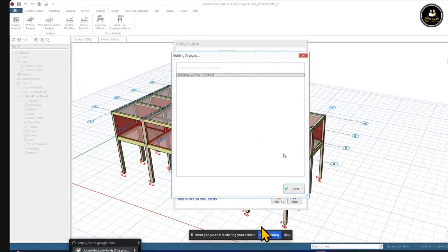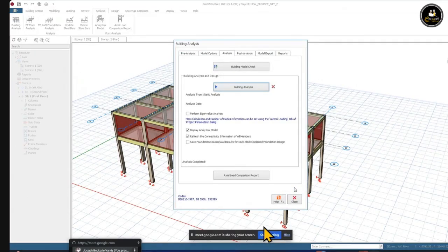Yes, hello. Just close. Click close. You can see the building analysis. It has some X. After design, it should give us a tick. So I don't know why it's not showing the green tick. It should be showing the green tick. Or maybe I was distracted. I didn't really follow what we did. Okay, well, it showed me something that the combinations were not defined. Oh, combinations are not defined. Let's just go and redefine it. Just close. That's why maybe it's not showing.